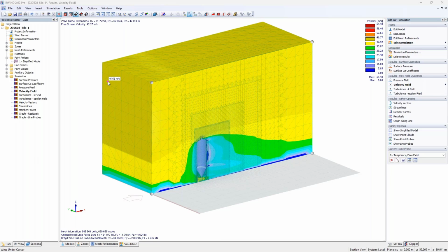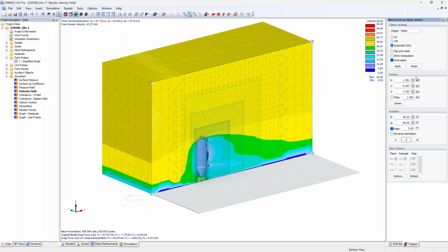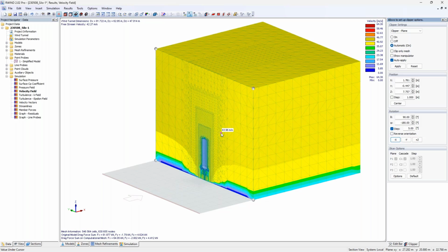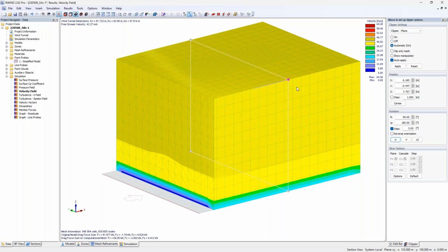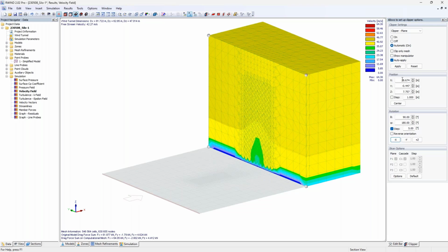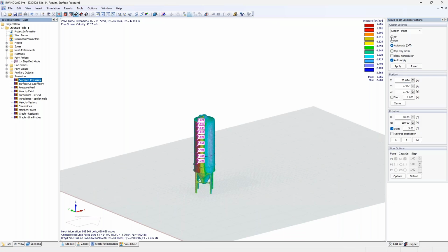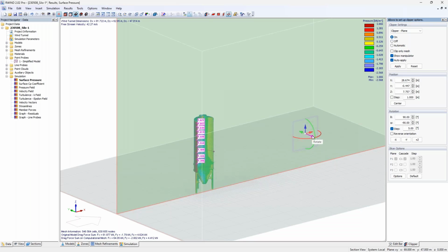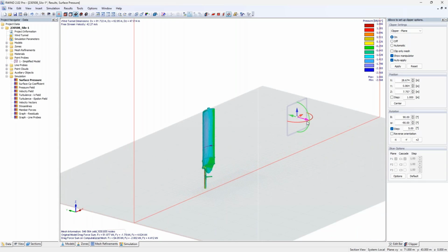Having a look at these results, we would now check the clipper, which is most likely a slicer, I think, for surface results. So what do we want to see? Yeah, I think it's the 3D results. You can quickly choose between some global axes by choosing the X, Y, and Z value in order to display some certain cuts. You can move the slicer if you want to have a cut like this. You can also set values over here personally, or you can also check 2D results, then checking for the clipper, activating it, and you can then also show your manipulator in order to move it if you want to move it in a certain direction. So it's up to you what you want to see, of course. So it's most likely cutting your structure, as you can see.